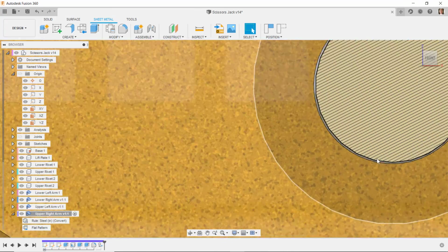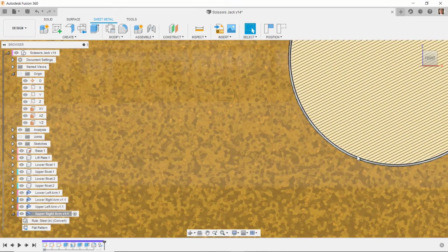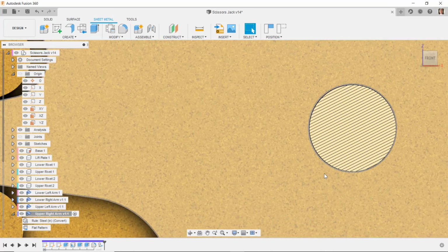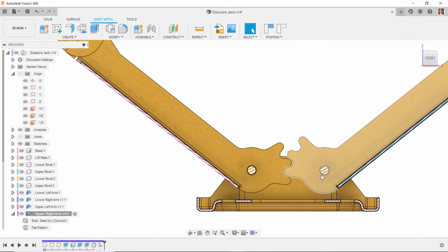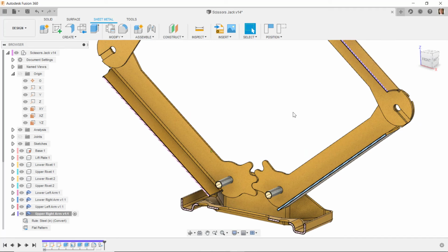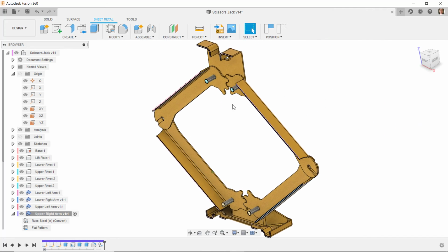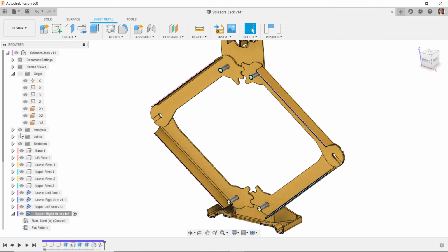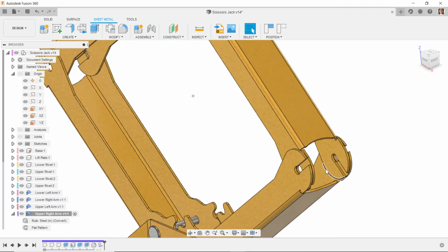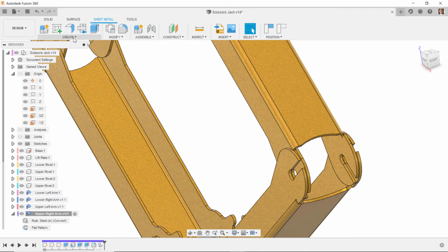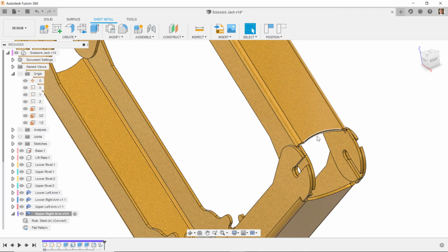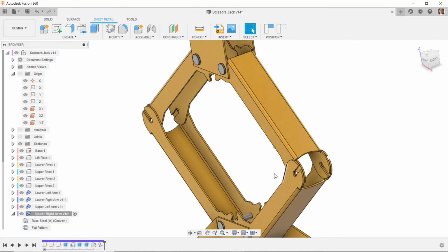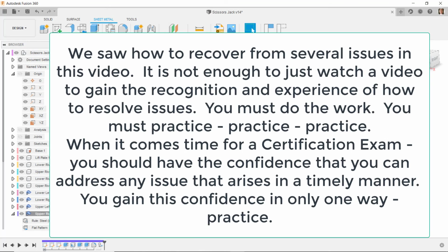Notice there's also a little bit of clearance between this pin and the hole in that part. There's another location where I want to check, and actually I guess we need more of the components in here. I'll leave analysis. So when we put the components that go across here, the hardware, we need to also make sure that they don't intersect here or here on these arms.